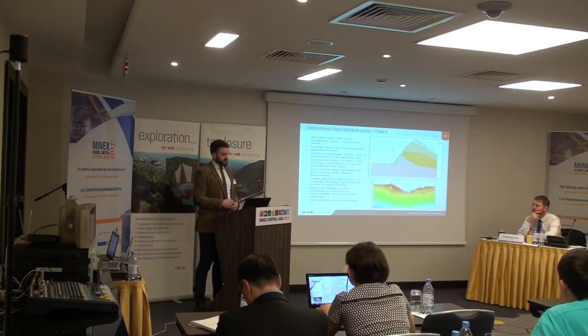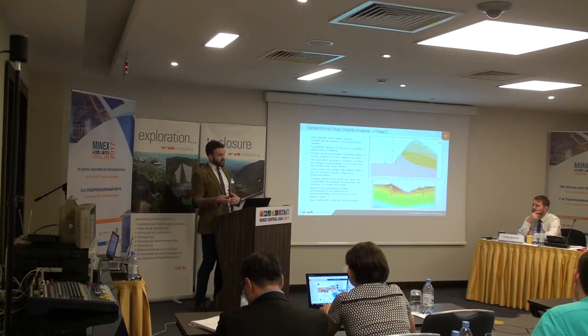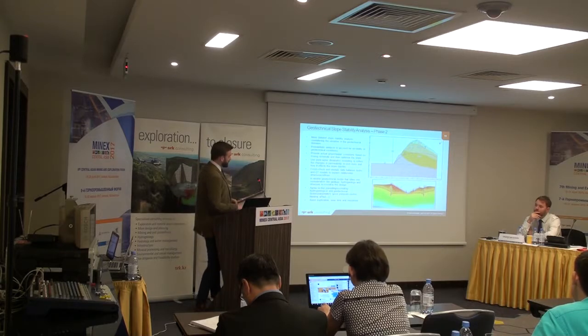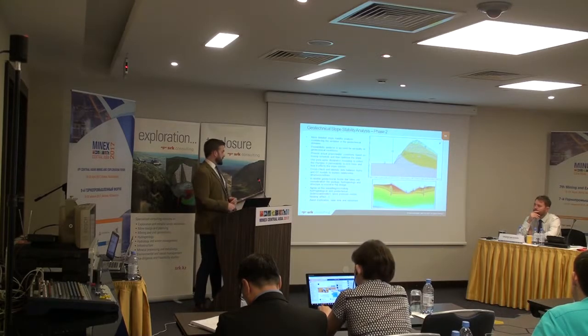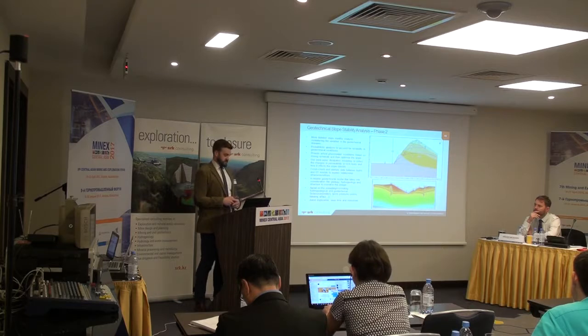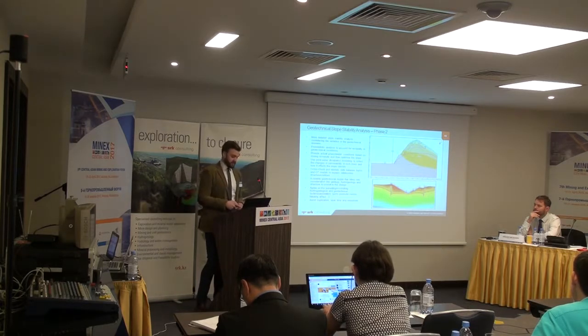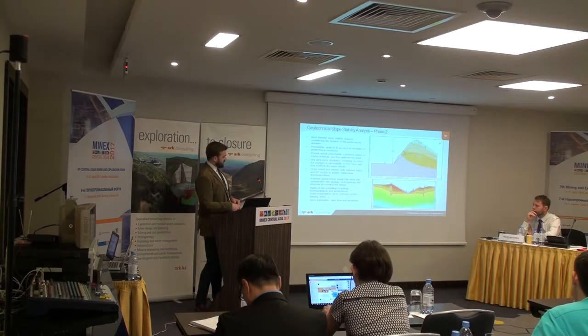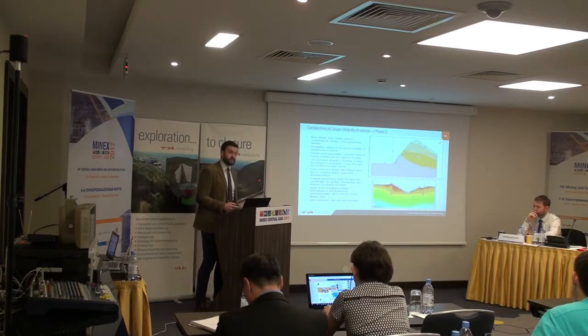And you must agree on the prevailing or controlling hydrogeological and geotechnical factors and parameters, and work out what controls the design, whether it's the pore pressure or whether it's a blasting effect. And again, I come back to this: avoid duplication, save time and resources. And this image here is just some pore pressure dissipation modelling to show how the change in groundwater conditions affects the pit slope design.